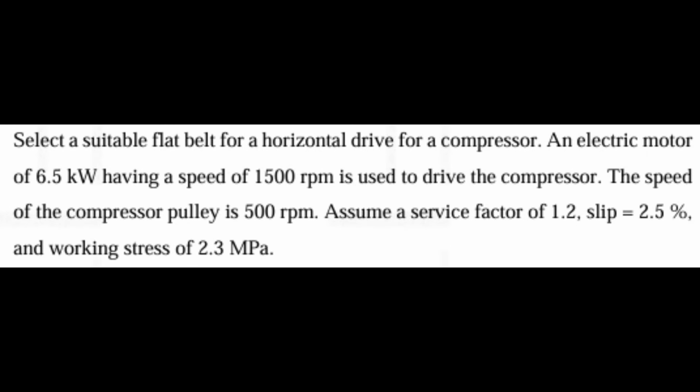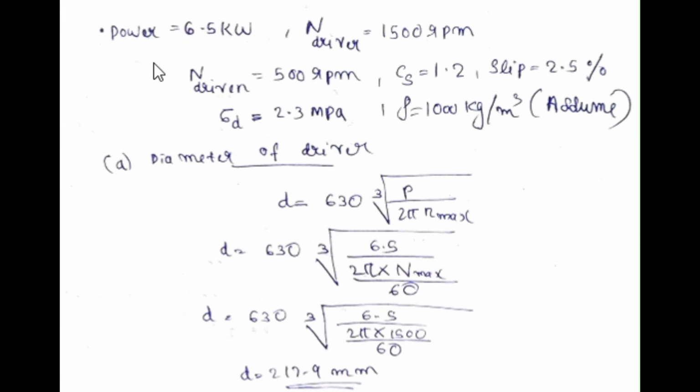The speed of that pulley, the compressor pulley, is 500 rpm, and the service factor is given, and slip is also given, working stress is also given. So you have to design or select a suitable flat belt based on these conditions. So these are all the given conditions.